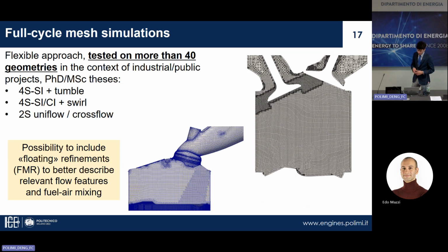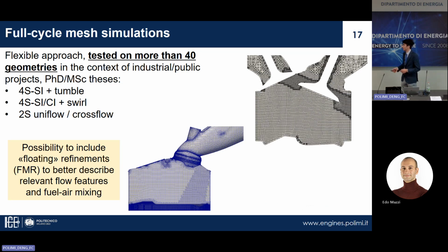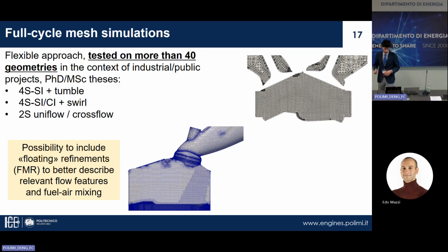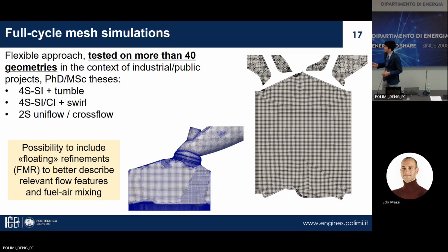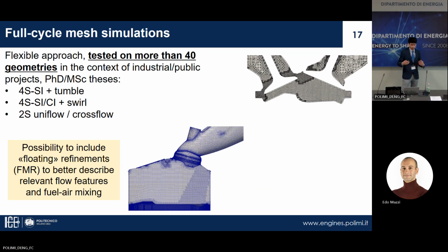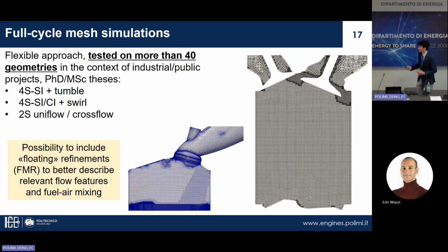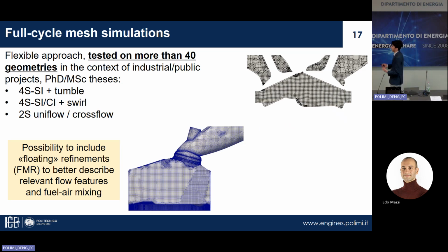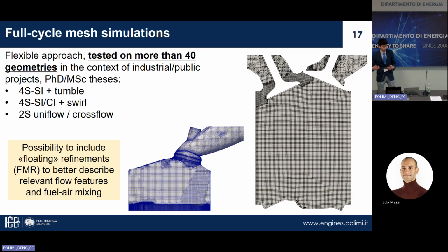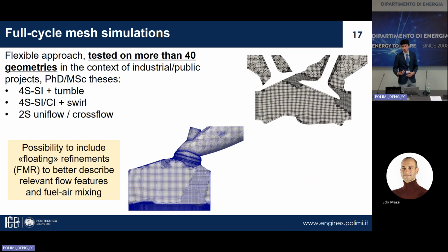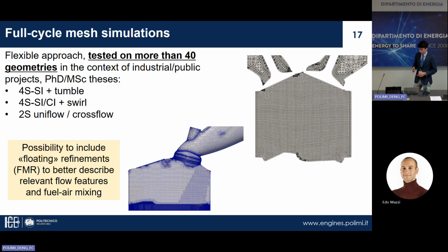We recently added also the possibility to include some floating refinement. You can see here an example. Basically, it's a refinement that follows the valve movement, to better describe some relevant flow features and to try to improve the air-fuel mixing.